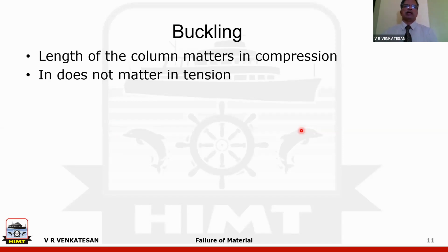And according to the stress, you will get a certain value of strain. And as the stress becomes more and more, it will go to a level where yielding will take place, plastic deformation starts, and finally it will go to a level where fracture can take place. And you will see the entire calculation, length does not come at all. So in the case of a component under tension, length of the part does not matter. What matters is only the cross-section area. Whereas in this case, you will see length also matters in compression.